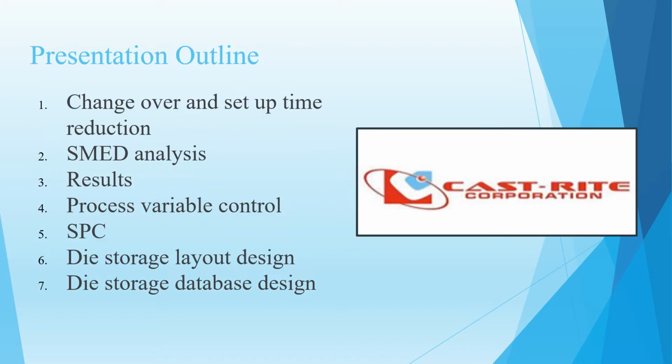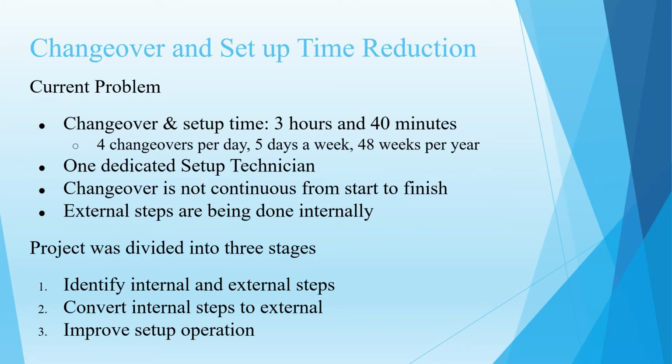Presentation outline: changeover and setup time reduction, SMED analysis, results, process variable control, statistical process control, die storage layout design, die storage database design. The current problem with changeover and setup at Cast-Rite is that the current changeover is taking 3 hours and 40 minutes. There's one dedicated setup technician, changeover is not continuous from start to finish, and external steps are being done internally.